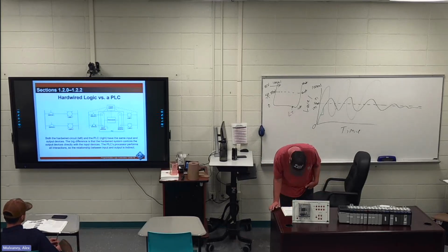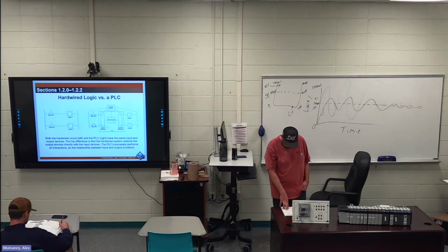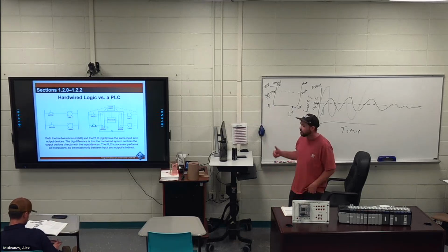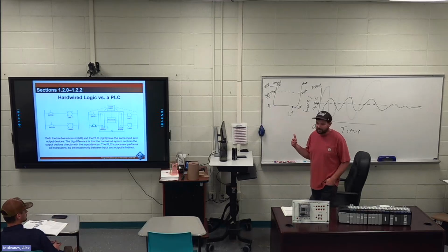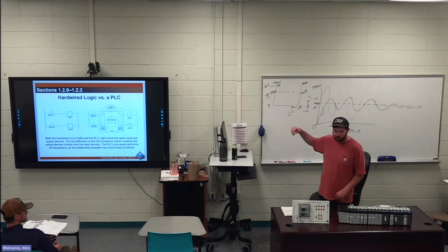Last paragraph on the page, last two sentences were highlighted. Many PLC inputs use devices called optic couplers to separate the inputs from the processor. These devices can protect the processor from voltages up to several hundred or even thousands of volts. So some knucklehead is running PLC input wire next to power wire that they didn't follow like what you're supposed to be doing, and it shorts together.